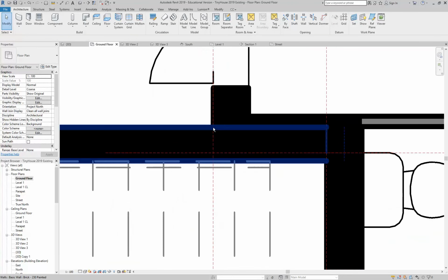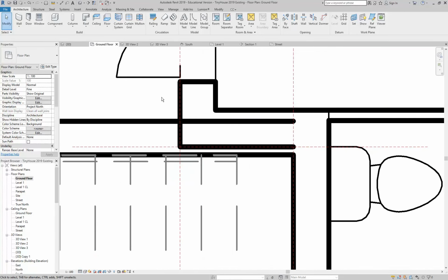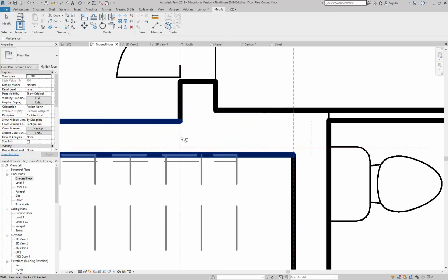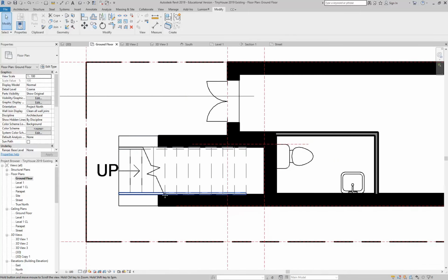If you're really super fussy though, like I can be, then you might want to make these walls blend together. So the very last thing I'll show you, this is optional, but a nice thing to know, and I think you've already done some of this using the join tool. You can join those walls and make them read as one. But in coarse, you're not going to see it anyway. In coarse display, it'll all come up black, which is probably what you'd want anyway.